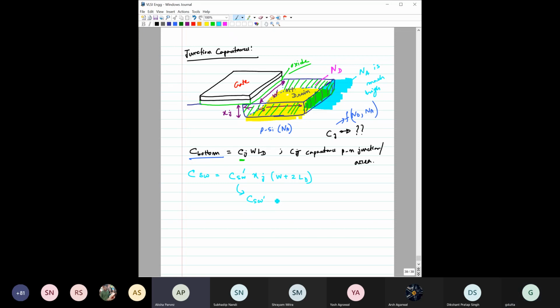Again, there's that oxide overlap over there, right? So that overlap might cause problems with the XJ into LD. No, no, Alisha, you are making a mistake here. Please remember, I told you this is junction capacitance. There is no role of the gate capacitance, right? We are considering only between this drain and this body. Okay, so then I don't see any major issue, right? Yes, okay, sir.